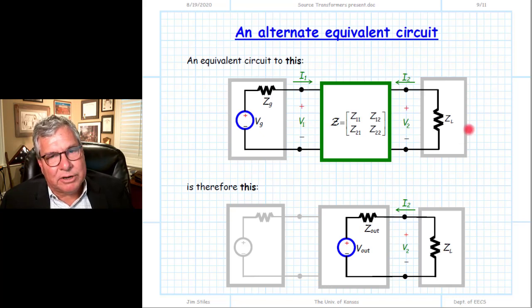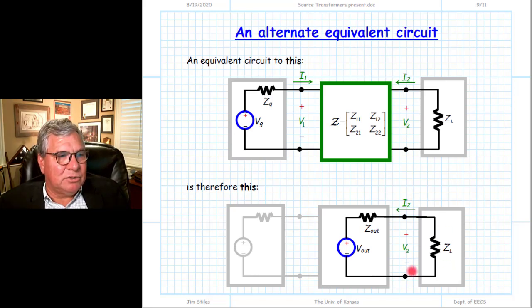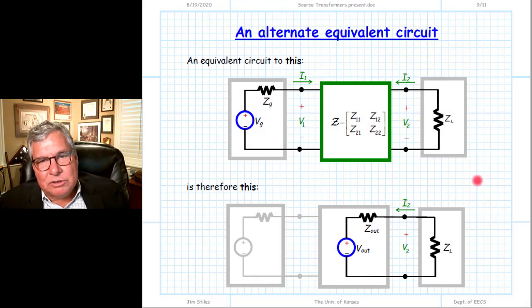How does a two-port device transform a load attached to it into a new impedance, which is the input equivalent of the entire circuit? Likewise, if we want to understand what's happening at port 2 at the output of our two-port device, the input to our load, we want to find I2 and V2, we could go through and again use our clunky coupled solutions, or we could say, let's draw a line in the circuit right here, divide the port plane. Everything to the right is an equivalent circuit. Well, that's just ZL.